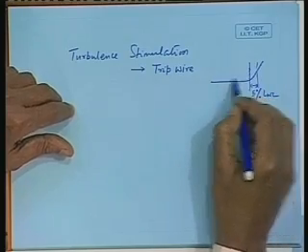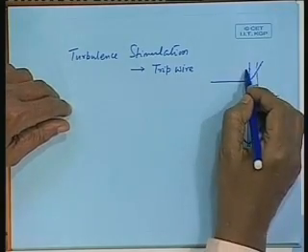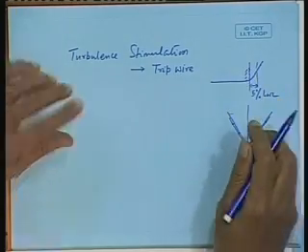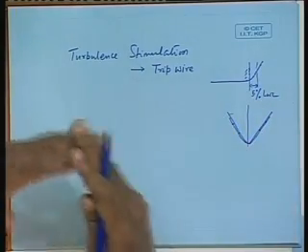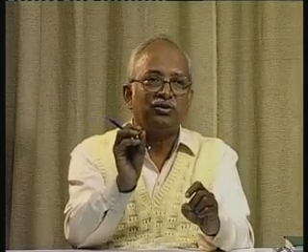Now, suppose I have put a trip wire here. What is the guarantee that the flow here is turbulent? The initial flow here will be turbulent, but because of pressure difference, we have seen there is a relationship between pressure and velocity. Because of such pressure differences, the velocity may further drop. If velocity drops, turbulence again may fall, because the local Reynolds number will come down again.